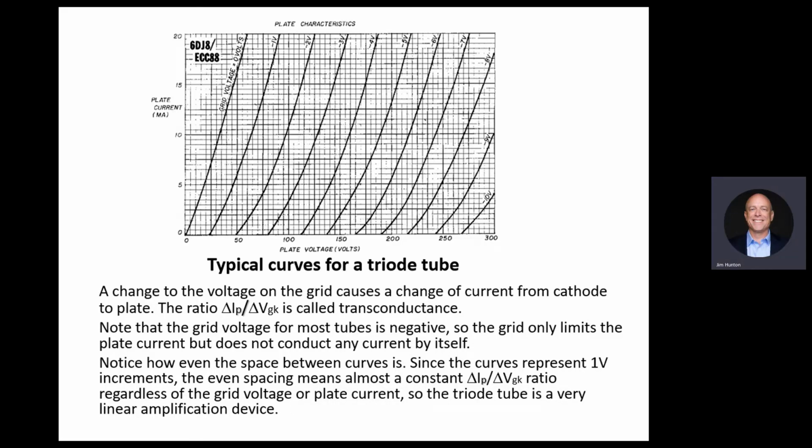Okay, so now we have a phono stage or any audio amplifier. We are bringing in that input sine wave, which is alternating voltage, right? It goes up and down. So that alternating voltage at any point in time, if we freeze it, is some voltage on this chart. Let's say we ended up at 0.2 volts, and we're using a plate voltage of 100 volts. We intersect those two, and we get something like 12 milliamps flowing in that tube. If we change it by 1 volt, we drop from here to there, a big change in current.